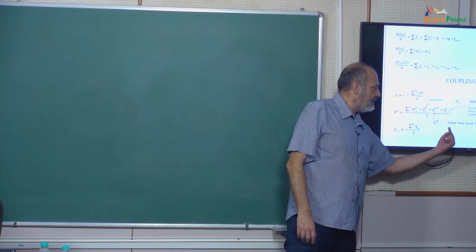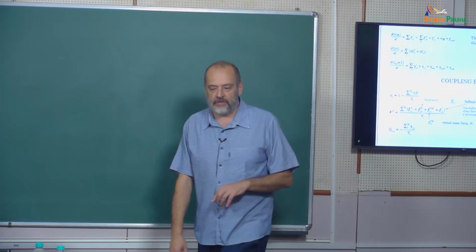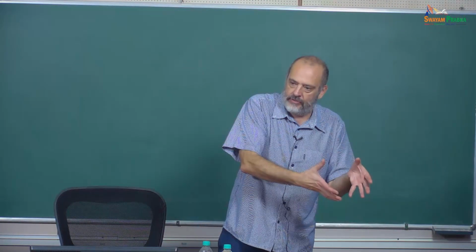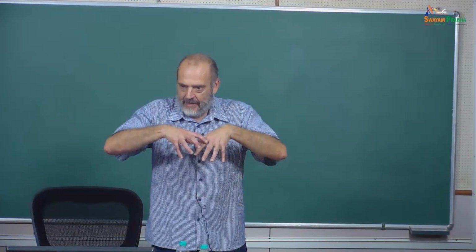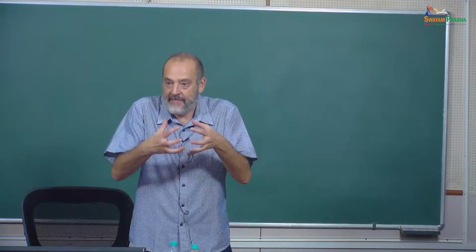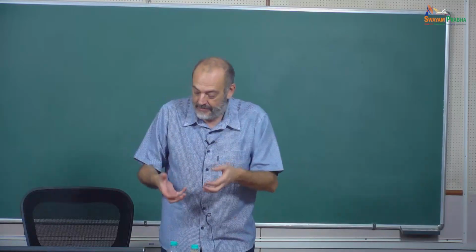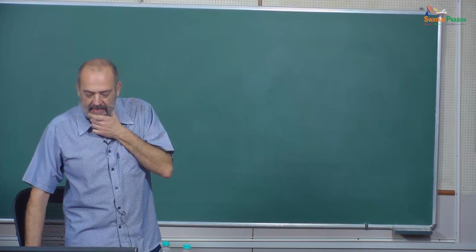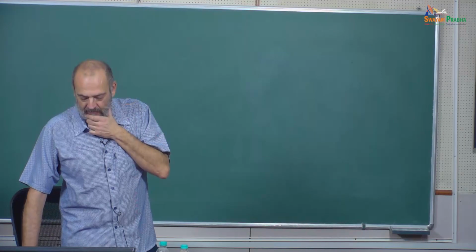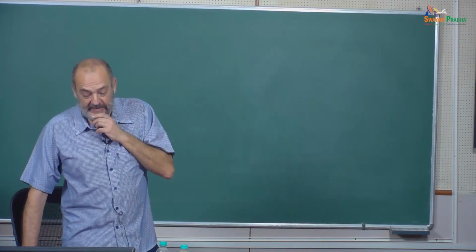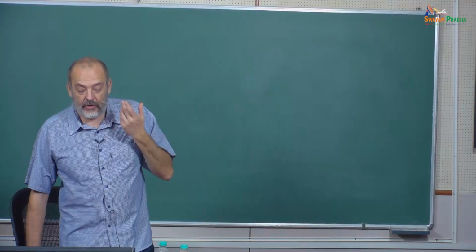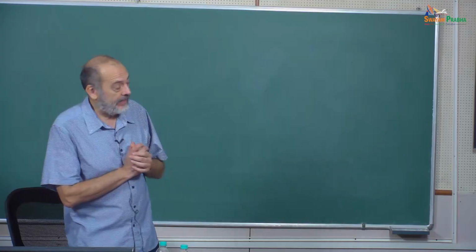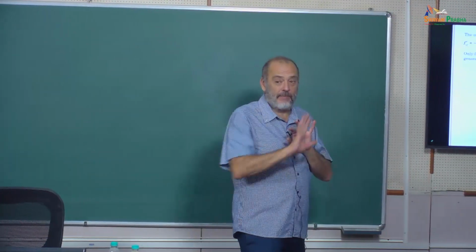And what is also interesting is that there is a virtual mass force, that is the force of the parcels together that are acting on the continuum, because the fact that we have, let's say, the dispersed flow is adding mass to the system locally. And this is, of course, something that we need to consider inside the so-called virtual mass force. Things are becoming really very complex because, for example, the contact force has a tangential and normal component, and then look at this. There are pages and pages of equations.